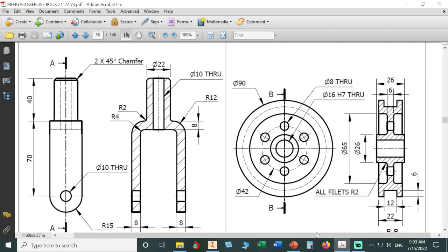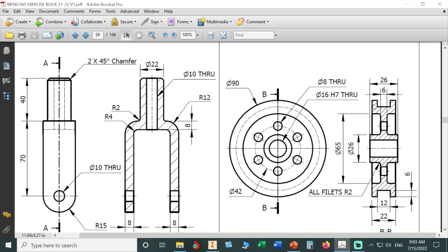You can see here this is our cut from both sides, so this 4 will be divided by 2. Then I'll cut 2 millimeters from here, from 90 to the end of 26.